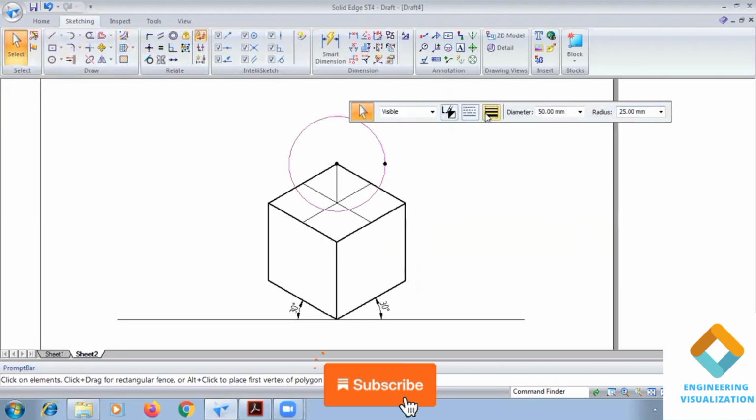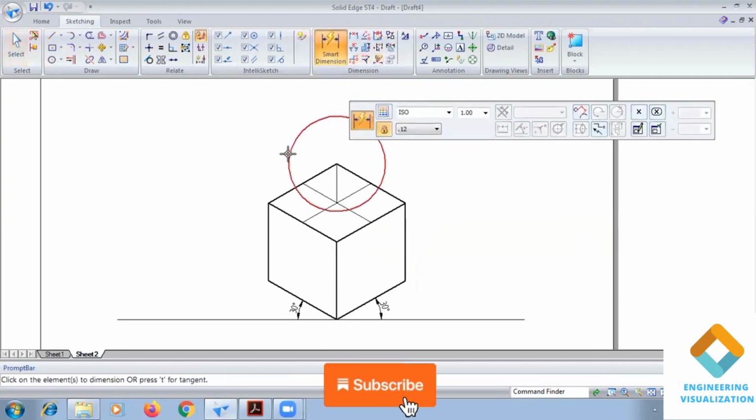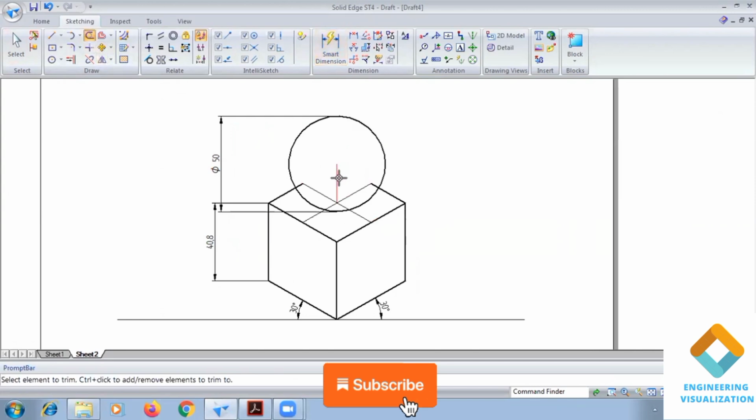So always remember, the sphere will be drawn with the actual scale, other solids will be converted into ISO. So you can check the dimensions here. This will be 50, the sphere's actual dimension, but if you check the dimension of the cube, it is less than 50. After converting to ISO, it is converted into smaller dimensions.